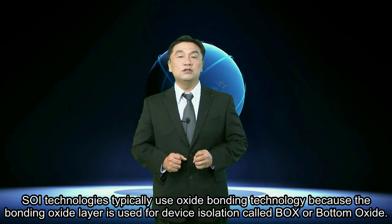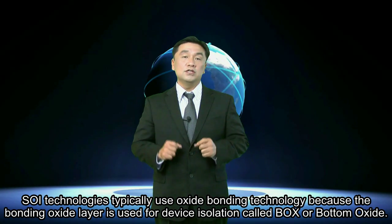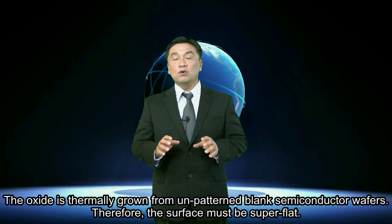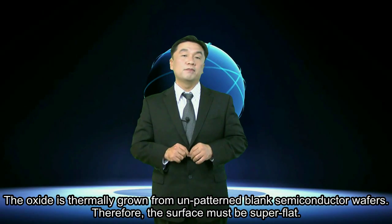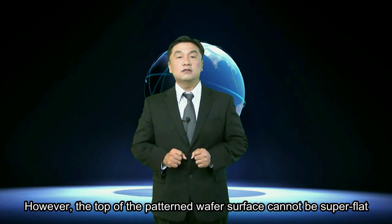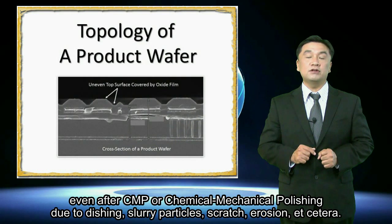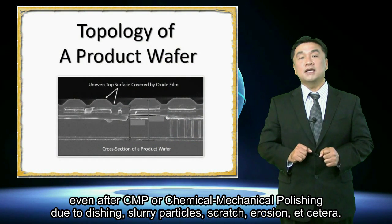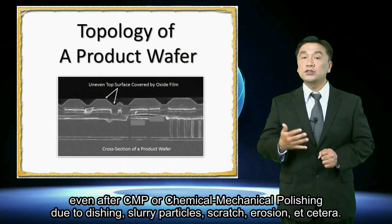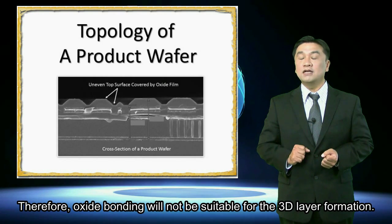SOI technologies typically use oxide bonding technology because the bonding oxide layer is used for device isolation, called BOX or buried oxide. The oxide is normally grown from unpatterned or blank wafers. Therefore, the surface must be super flat. However, the top of the patterned wafer surface cannot be so super flat even after CMP, or chemical mechanical polishing, due to dishing, slurry, particles, scratches, erosion, etc. Therefore, oxide bonding will not be suitable for the 3D layer formation.